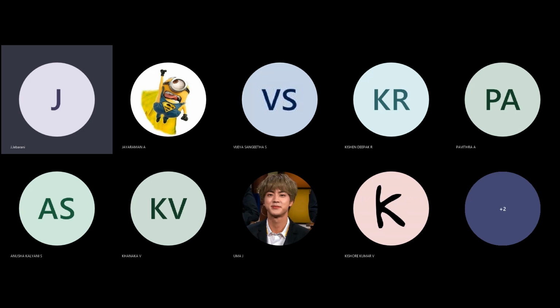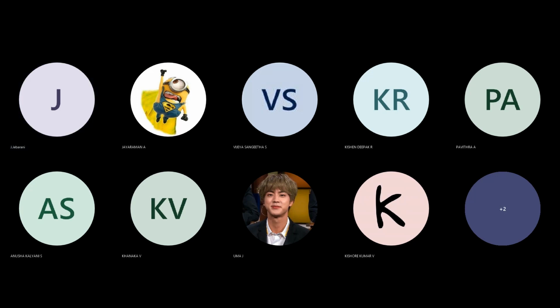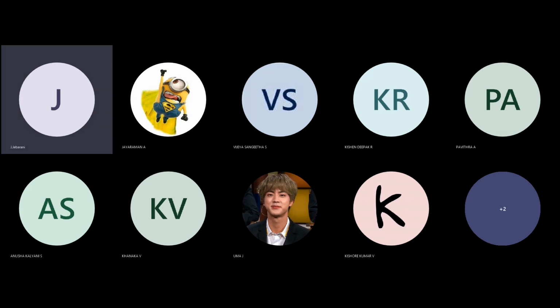The advantages are material savings and a high rate of cooling. Disadvantages include blemishes that occur at the tip of the part. Also, the low pressure could cause water to seep between the inner mold surface and the outer part surface.